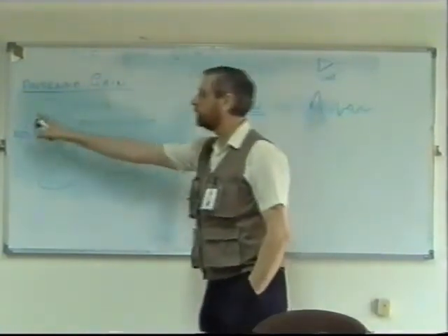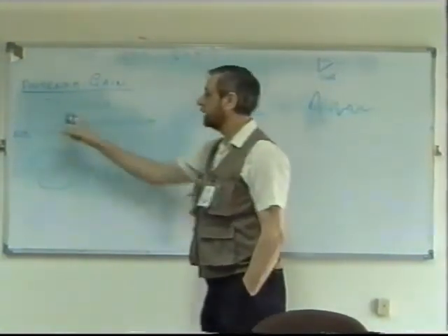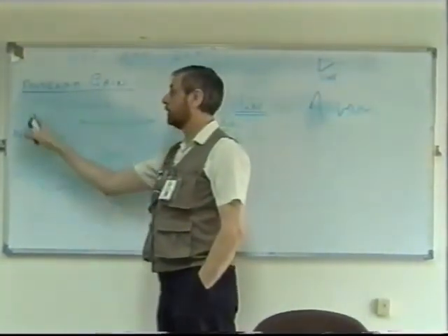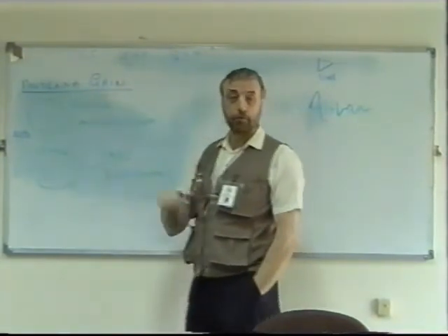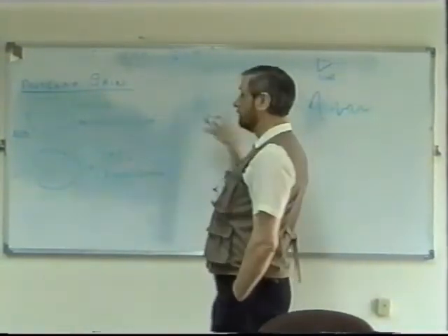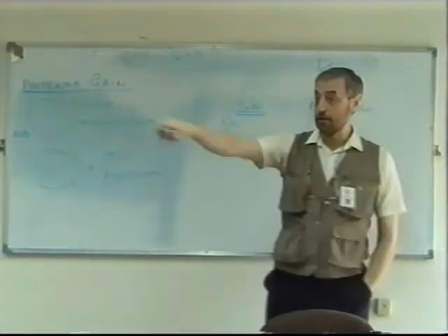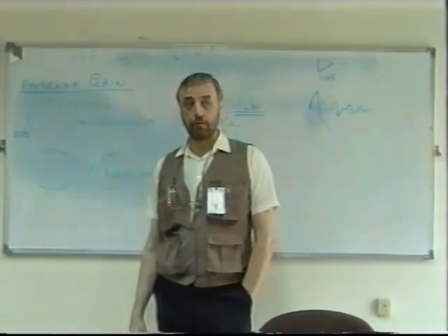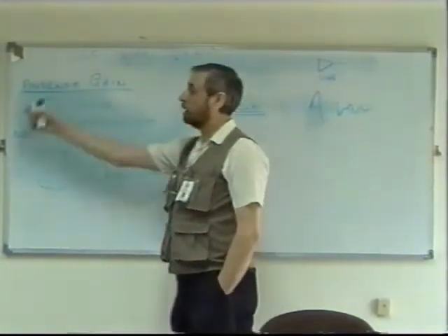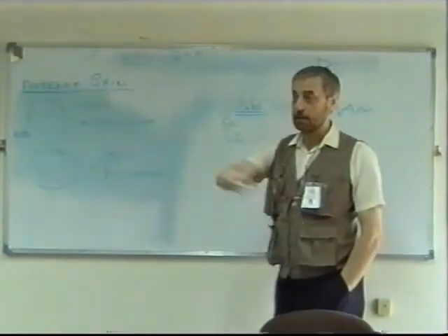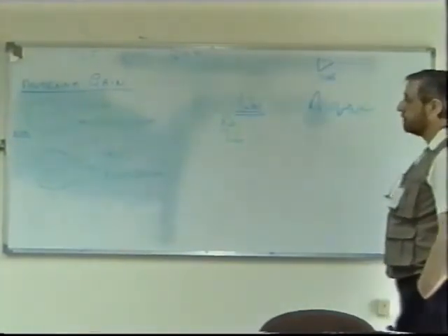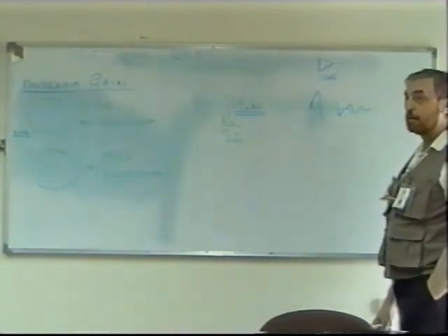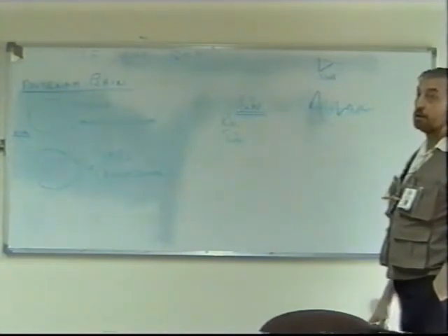Okay, now there's one example, using a dipole, omnidirectional antenna. We would probably have to use a dipole, or at least a stacked array, if we were communicating on a mobile basis, because the receiver could be anywhere around the antennas. Yeah, we would have to make it at least omnidirectional in the azimuth anyway, at least in the horizontal.